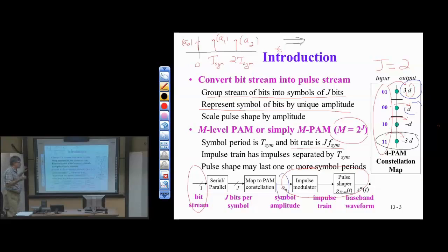It's whatever the pulse shape is, right? It's a sequence of pulse shapes now, and those pulse shapes are going to be scaled by A1, A2, A0, A1, A2, etc. If I were to use a rectangular pulse, which is the easiest one to draw, so if you really have to draw one on a test, go with a rectangular pulse if you have the choice. It's the easiest one. So I'll have A0 for a while.